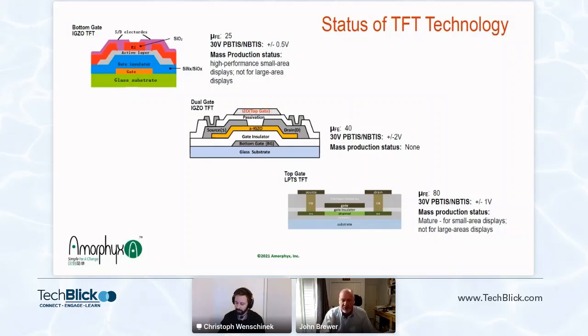Laser annealing amorphous silicon dramatically increases speed and output current, while dramatically compromising stability and manufacturability. In response, the display industry developed compound semiconductors, metal oxides, specifically indium gallium zinc oxide, IGZO, to improve speed and output current without compromising the other parameters.